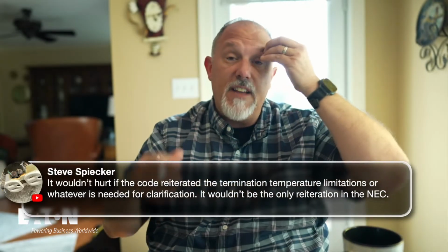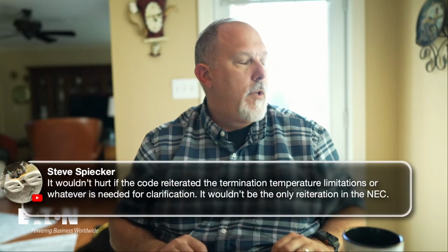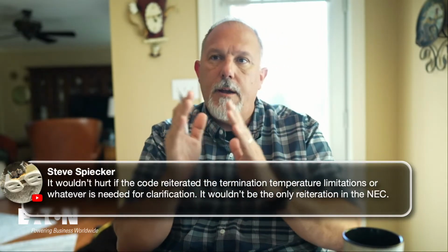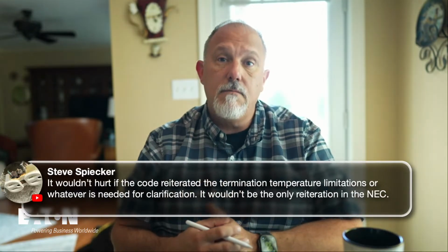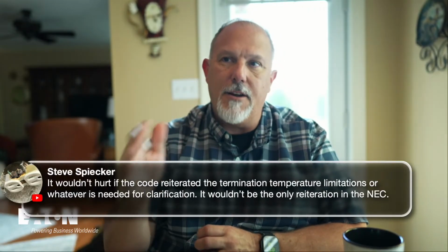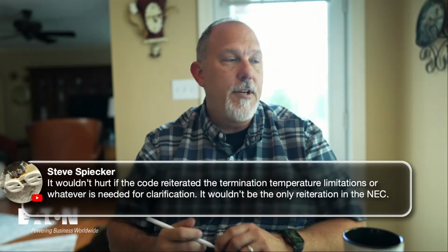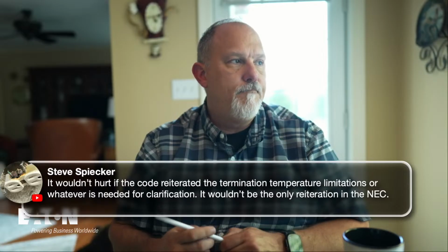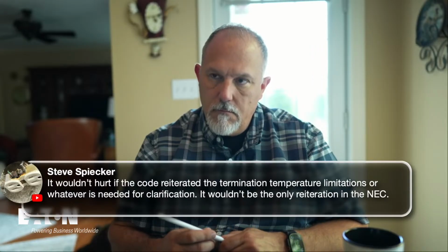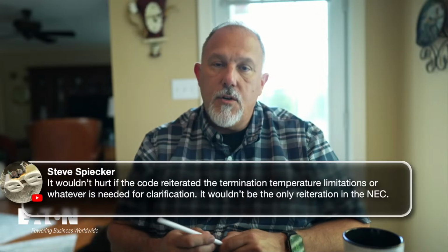If we're doing the 125% because of my locked rotor amps and that transition from locked rotor to full load amps might have a heating impact, like if it's on a conveyor belt, but the application doesn't come into play here. They're just simply talking continuous duty, like a continuous load. I'm not going to worry about that. But I agree with you.